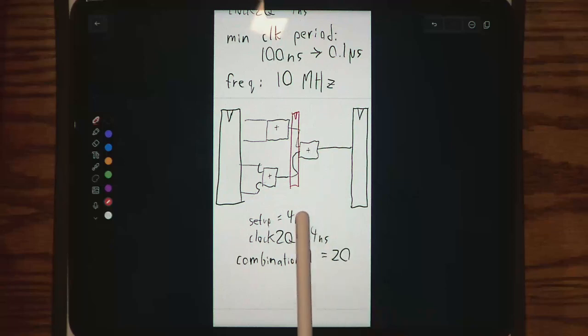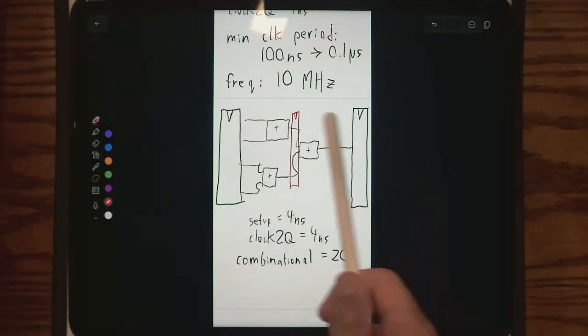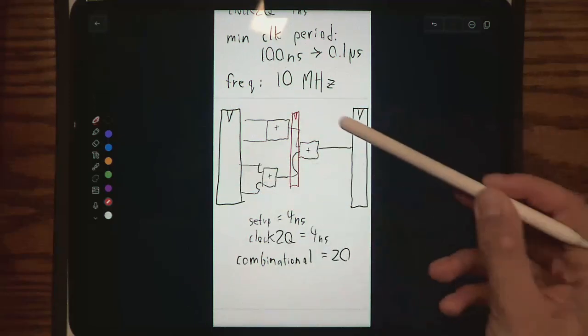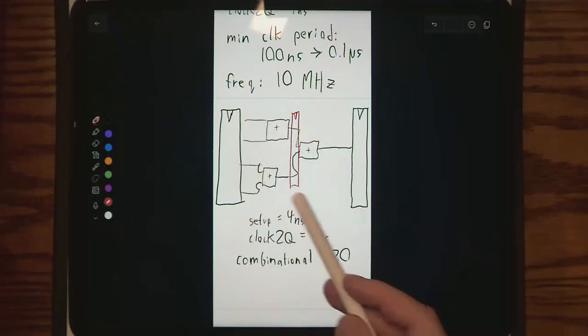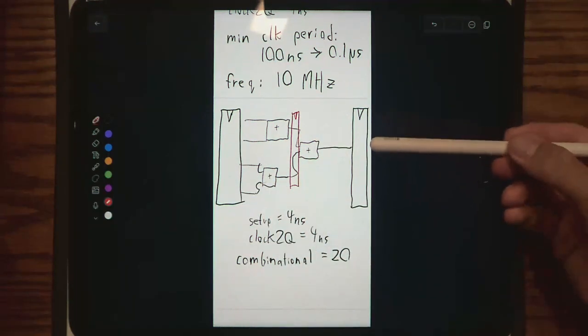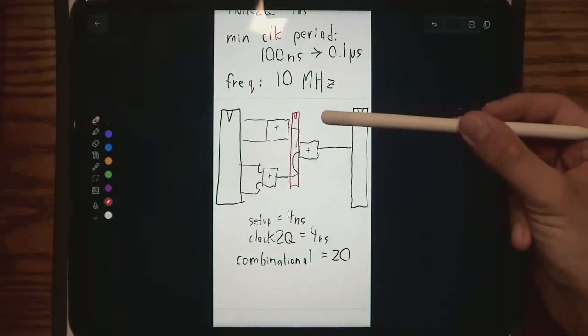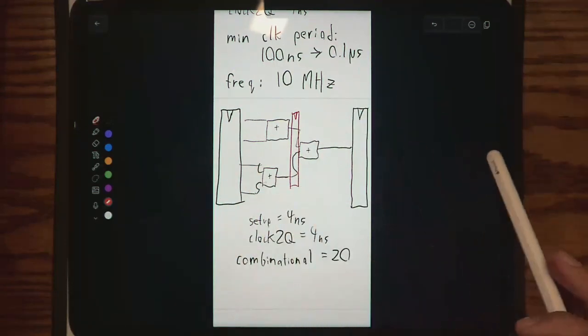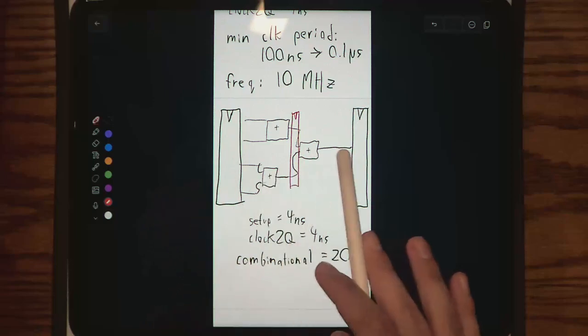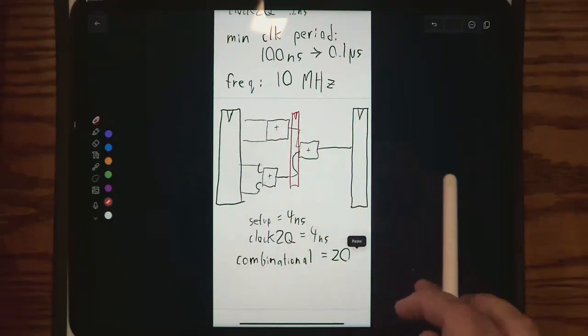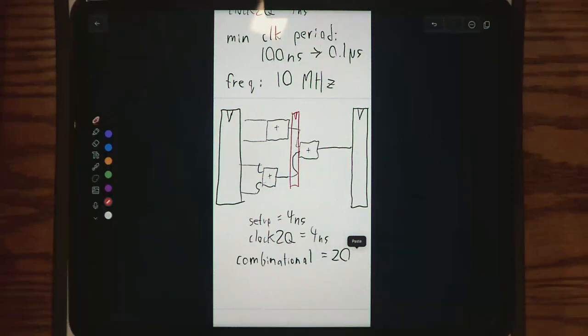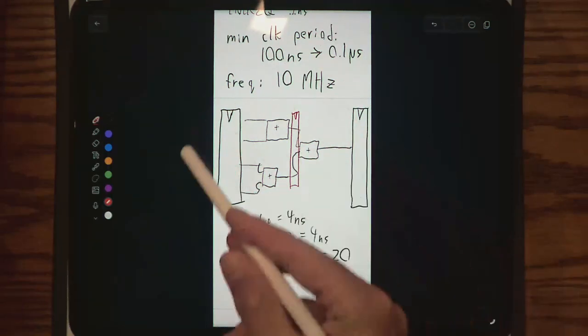And then maybe at the end of it, maybe we call this circuit, I don't know, adder for whatever, CSE100 or something. We gave this circuit a name, and then in the data sheet for it, we just specify this circuit will take an extra clock cycle. It'll take maybe a total of 3 clock cycles, one for the input, one for an intermediate pipeline stage, and one for the output. So maybe we just say that, and so now people have the responsibility to use your circuit effectively.